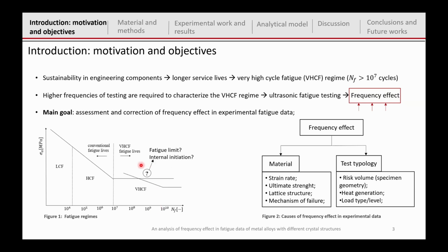However, to analyze this regime, we need to test our specimens at very high frequencies, and usually for that we use an ultrasonic fatigue testing system that I will speak about during this presentation. Because of that, sometimes we have in certain materials a thing that we call the frequency effect. This frequency effect can be caused by different factors and aspects. Usually in literature, we can divide these into main groups